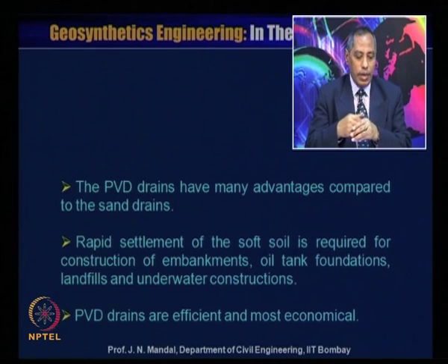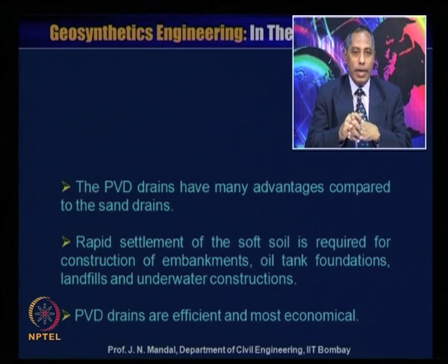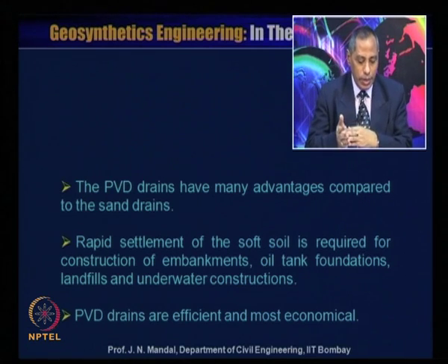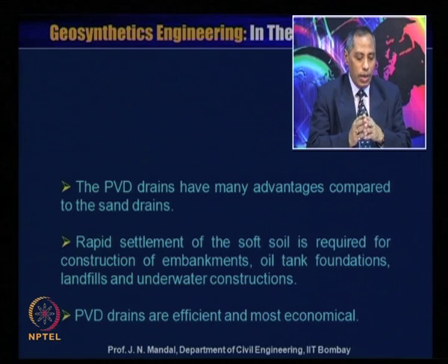Apart from that, due to the surcharge load, there is a possibility of shear failure of the foundation soil. And in addition to that, as you know, the small diameter of the sand drain offers no shear resistance of the soil.